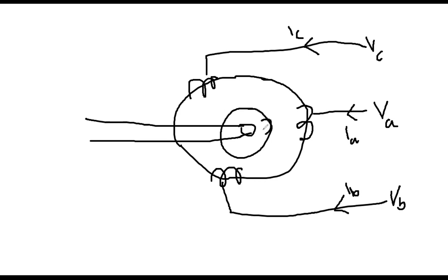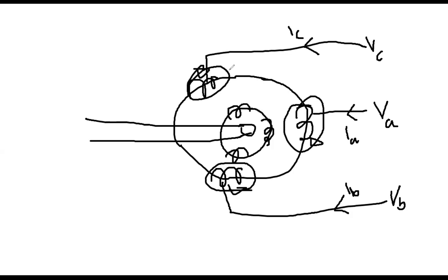And then there is another set of coils on this body. This body is called the rotor body, to which the shaft is connected. So still the shaft is not rotating. Initially the shaft is stationary. Now everybody see the operation. Once you apply the three-phase voltage, in other words, the three-phase current is flowing through three sets of coils. What is the consequence of current flowing through a coil? It will produce flux. So this is producing flux here, this is producing flux here, and similarly this current is producing flux here. And if you combine the three sets of flux, then you will see